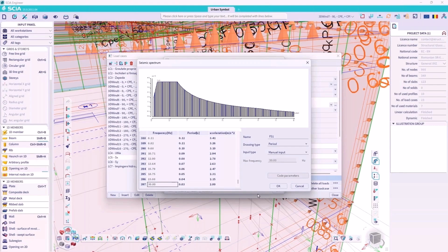So in this way, we ensured everything because Romania is a seismic area, and we wanted to understand the whole behavior of the structure. So we wanted to get the real stiffness of the steel connected to the glass and connected to a concrete infrastructure that is positioned on top of something existing. So this is the reason why this 3D global analysis was a must in this project.